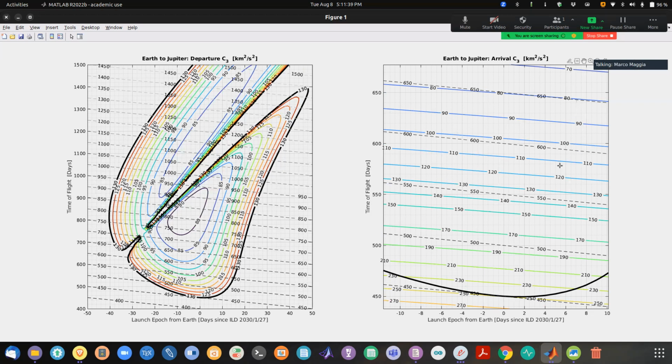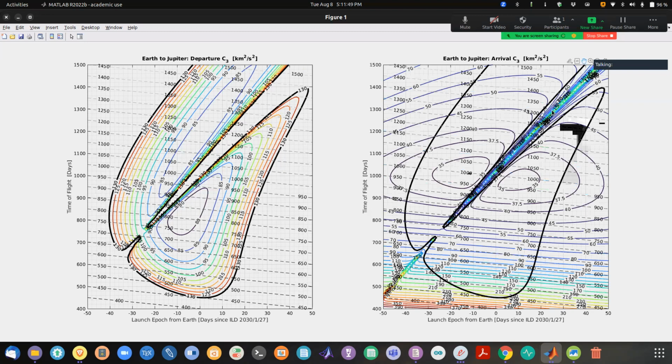One thing that you could do now is to take a screenshot of this Porkchop plot, which I've previously done, because then we'll need to compare the right-hand side of this Porkchop plot pair to the left-hand side of the new Porkchop plot pair. One more thing here, these straight lines that are slightly diagonal and dashed, they indicate the amount of days after the 0, that is our ideal launch date, ILD.